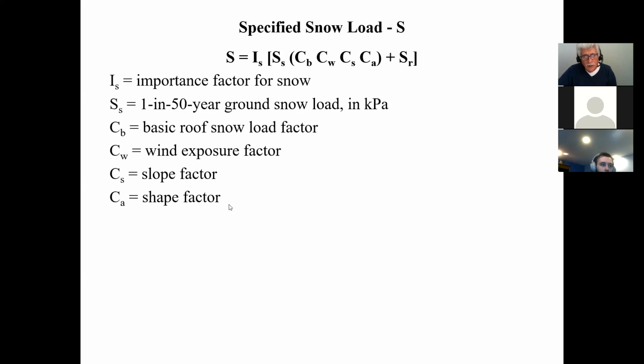So what happens is that not all roofs have a very uniform load, depending on what's obstructing the snow or how the roof is shaped. It can have a non-uniform load, and this is what this allows for. It allows you to calculate what that accumulation, or that shape that can accumulate on your roof, can come out to weigh. And we will talk about this for a very particular situation. And the SR of 1 in 50, in kPa.